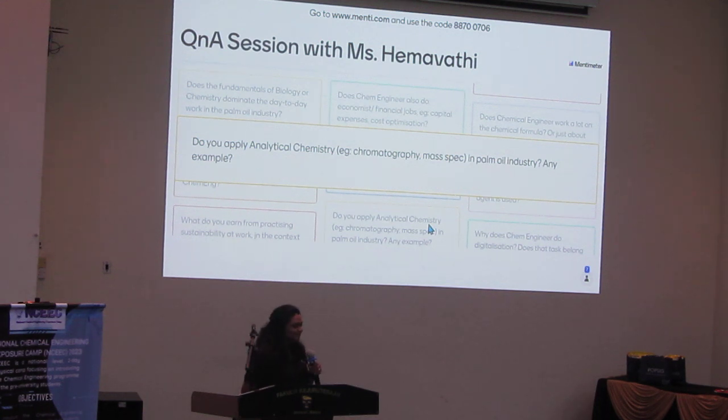Nice, okay, yeah. So again, it goes back to the process. I showed how we do the palm oil processing, for example. If I want to improve a certain stage of it, for example to introduce enzyme, I'm trying to increase the extraction rate, but I cannot only look at the output. So I actually do certain chromatography, for example liquid chromatography, HPLC, gas chromatography.